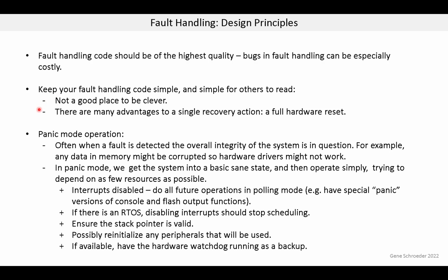There are many advantages to a single recovery action, that being a full hardware reset. I like to do that if it's acceptable, and that's what we do in this course. If you do something less than that, like let's say you are having problems talking to a sensor, so you reinitialize an I2C controller, then normally, if that doesn't work, you later have to escalate to a full reset. And that is a much more complex design. Of course, sometimes you really need to avoid a full reset if at all possible. So it's worth it to start small and escalate only if you need to.